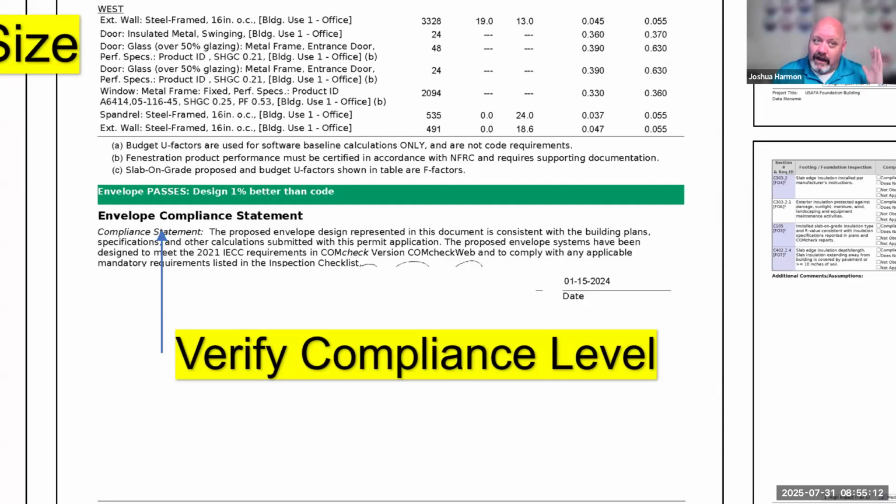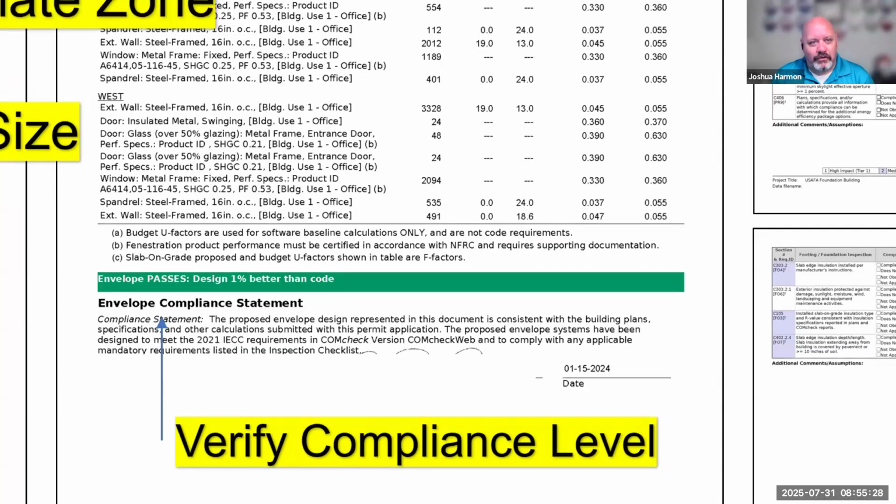And I said, well, hey, that's up to you. I don't trust anybody's level of consistent installation to work on that skinny of a measure of success, right? What if they don't put in R13 continuous, they only put in R10? That's going to affect you. You might not be able to see it today, but you will get that phone call later when somebody comes back and says, wait a minute, I was looking at the records, you were approved at R13, but the material that's installed says R10. How did that happen?